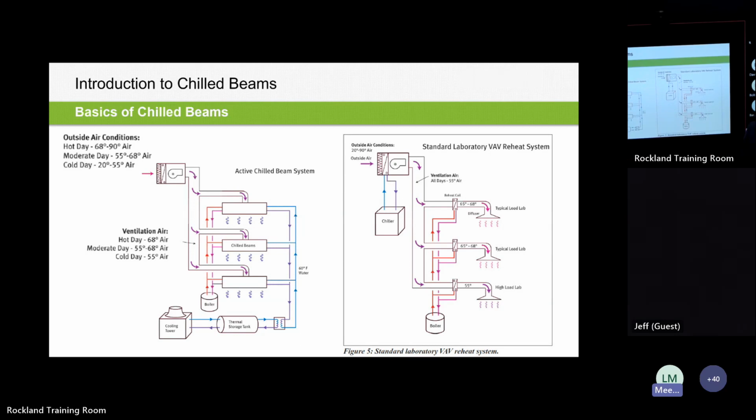Right. Yeah, so you would design it for your min and max conditions and make sure that the plenum pressure within the chilled beam stays within range, which is critical for us. So operating between 0.2 inches and 0.8 inches of water column, and making sure that those conditions you're mentioning are within that range, and you won't lose induction rate, you won't lose detachment or Coanda effect, and things like that. Yeah, very good question.